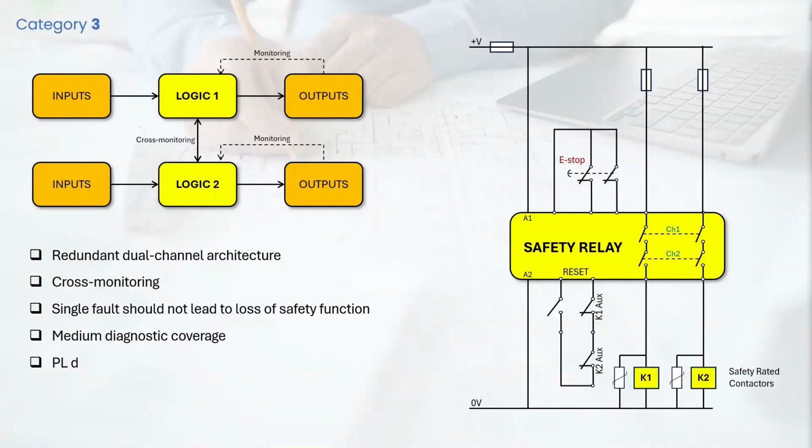In both cases, the safe state is maintained by opening two internal dual-channel NO relay contacts. The force-guided output relays K1 and K2 directly support this architecture. Their mechanically linked contacts ensure that if a contact welds, the mirror contact cannot close, making the fault detectable.